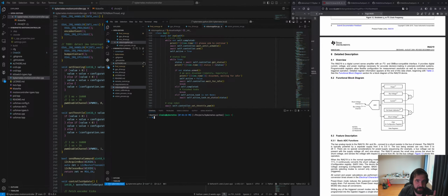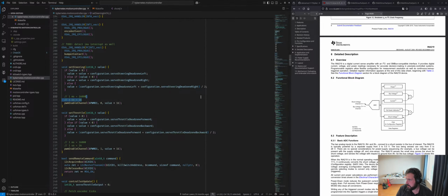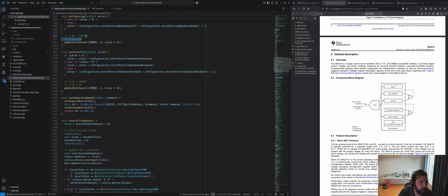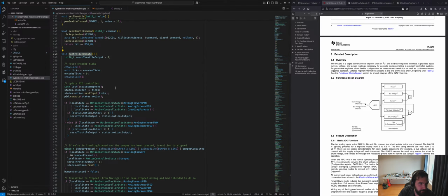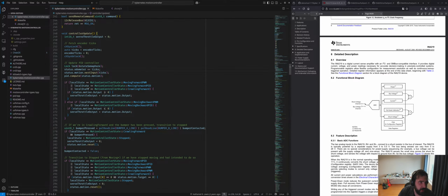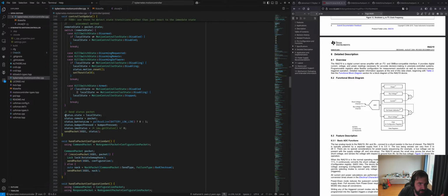I think what we'll do, where we'll start at least, is I have a status message that is sent 50 times a second, every 20 milliseconds, from the motion controller to the Raspberry Pi. That is done through this controller update task. It goes through here, it reads the encoder, does some stuff, updates PID controllers, and eventually comes down here and sends a status packet to the robot.